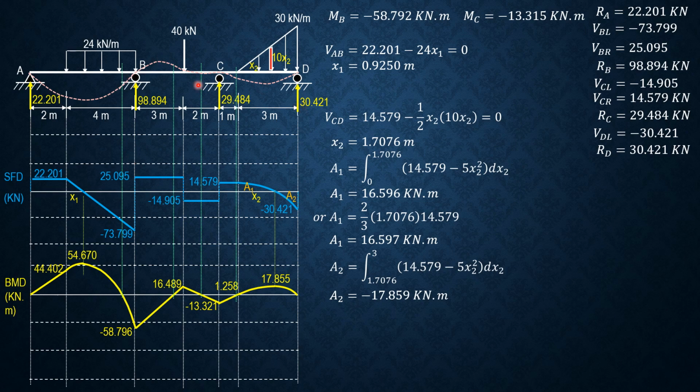So again, what is important is the curvature. But for obvious loadings, the elastic curve should be clear. For obvious loadings like this, it should be below the horizontal axis. But here, if you cannot anticipate that it is above, as long as it is concave down for this portion, that's acceptable. But the correct or accurate way is you solve the deflections, representative deflection at each span of the beam, but that's a long method.